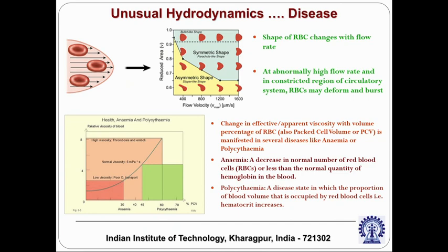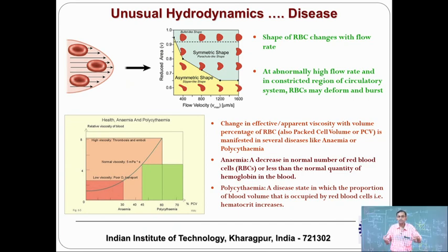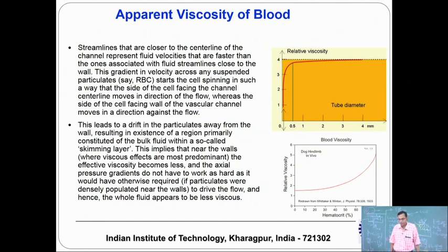Now, the hydrodynamics of blood flowing through a microfluidic channel may be affected by certain diseased conditions, but even without that, a very important aspect which I want to highlight is the Fahraeus-Lindqvist effect. So, what is this effect? If you look into the top graph in the figure, you will see that as you reduce the diameter of the blood vessel, the apparent viscosity, instead of increasing, actually reduces.